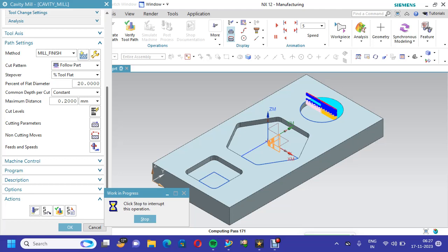Here we are explaining how to trim boundaries. That is the important thing. If you keep this side, it will go to outside. Now if you want to trim inside, then I will explain how to change it. Whether you are going to trim inside or outside, that is the main point. If you put inside, the cutter will take place outside. If you put outside, the cutter will take inside.